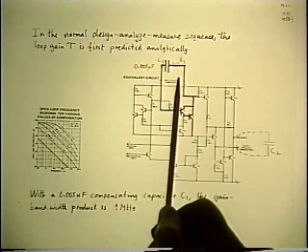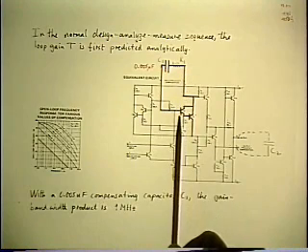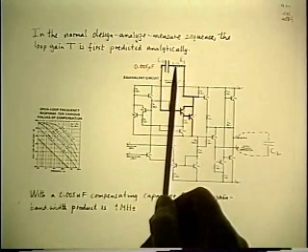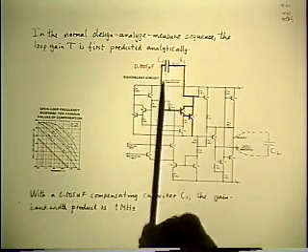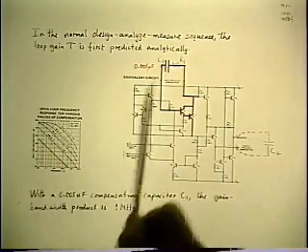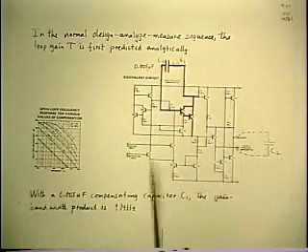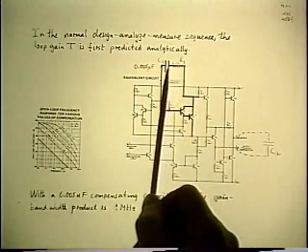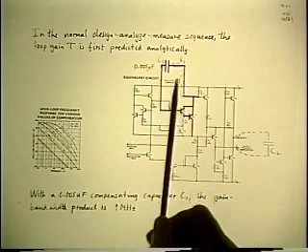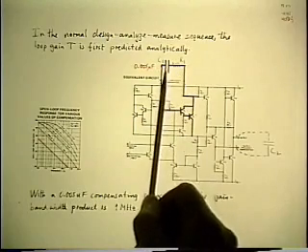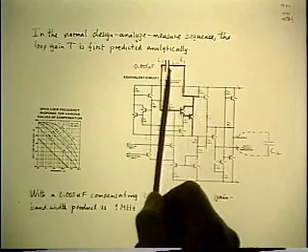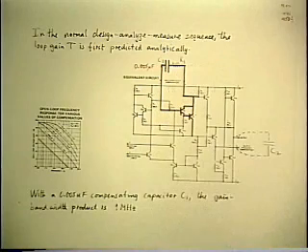Now, when I looked more carefully at this data sheet, you see that I did something wrong in the design, because the data sheet said I should have put a resistor there as well. In fact, it's labeled on these asymptotes. I neglected to do that, on purpose, of course, in order to illustrate this point. Because what happens if you put a resistor in series with that cap? It limits the effect of the capacitor. In particular, as frequency goes to infinity, the cap will become a short, and you'll be left with the resistor.